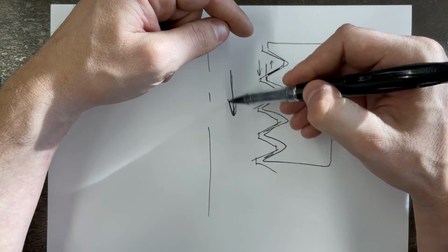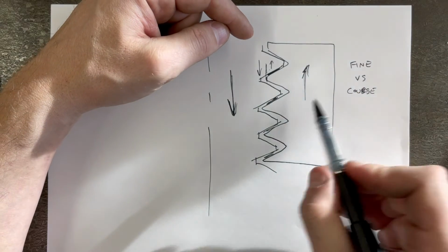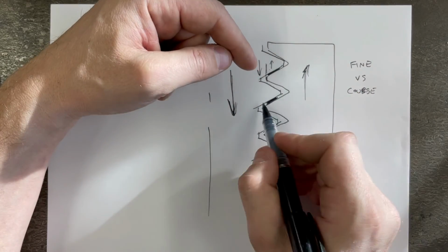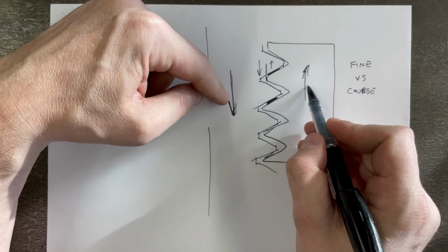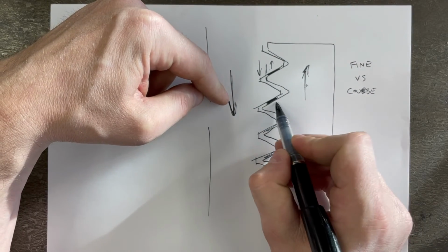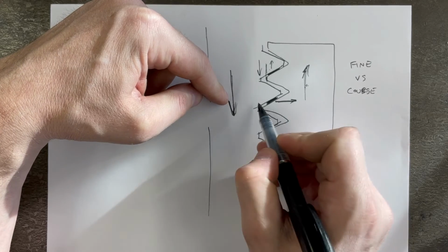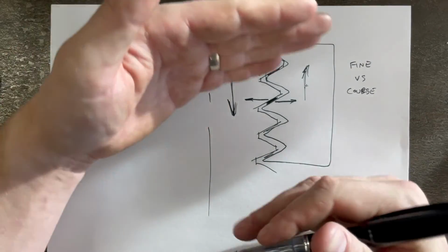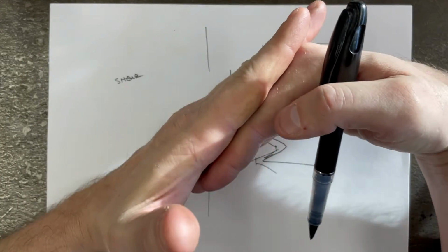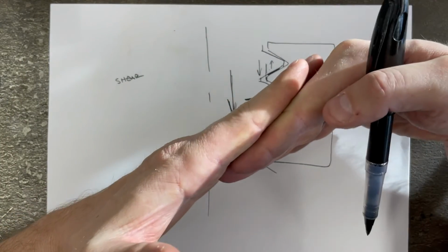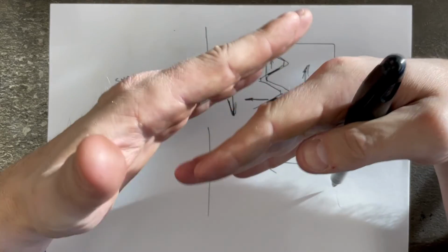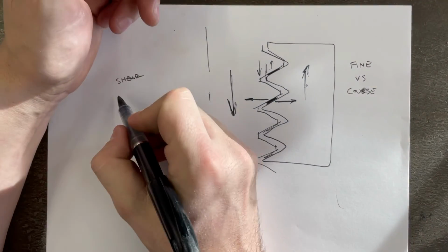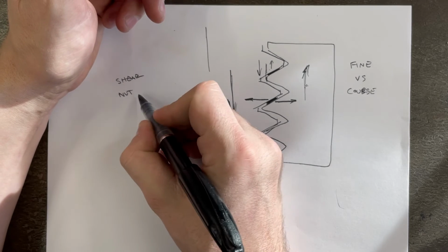If we have this one coming down and this one going up, and it's acting on this angled surface, what's going to end up happening is a portion of this is actually going to be pushing the nut out this way, and part of it's going to be pushing the threads of the cap screw in that way as well. It's like a wedge, right? It'd be like if I had two wedges and I'm pushing them against each other, they're going to slide. They can't go down, but they can stretch outwards. So that's something called nut dilation.